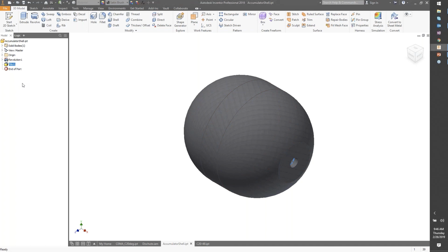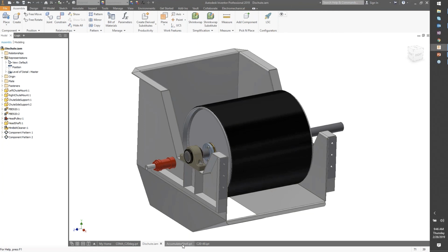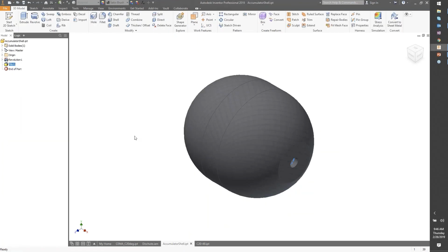If this is a vendor component and they make a design change, I can adhere to those changes as well. And now that I have all those individual components out there, I can use my normal iLogic just to swap those components in and out. So it's another means of doing the exact same thing that iParts and iAssemblies can do for us, but without the worry of that impact to performance.